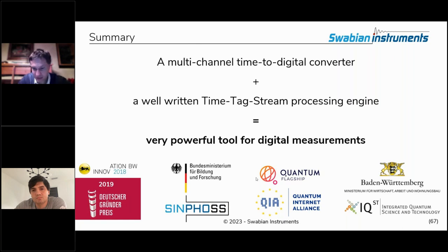Besides these really high-end measurement applications, there's probably one thing that is quite relevant, and that's power consumption. These FPGAs have a huge power consumption, and as a lab measurement tool, that's fine. You don't worry so much about whether this thing consumes 10 watts or 100 watts. But if you have a TDC chip that is very accurate and part of some embedded measurement system, or a LiDAR sensor in a car or whatnot, it may be very important that the power consumption is low. So there might be a completely different market for TDC chips with high precision and low power consumption in embedded measurement systems that I am not aware of yet. And I somehow have the feeling that this may be, at the end of the day, one of the wider applications. Does that answer your question?